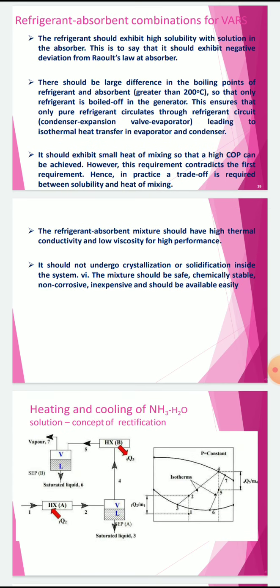The refrigerant absorbent mixture should have high thermal conductivity and low viscosity for high performance. It should not undergo crystallization or solidification inside the system. The mixture should be safe, chemically stable, non-corrosive, inexpensive, and should be available easily.